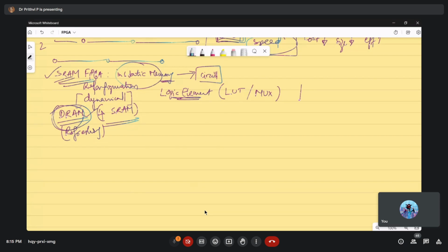Normally when we take an n-to-1 mux, the number of selection lines m is such that 2 power m should be equal to n. For a 4-to-1 mux, that determines the size of the lookup table. Let me put that into a schematic. Say this is your lookup table, which is able to give 2 power m combinations of inputs to a mux.